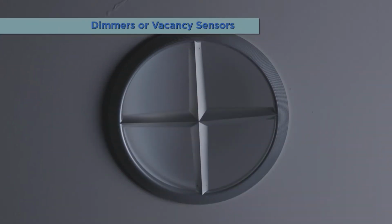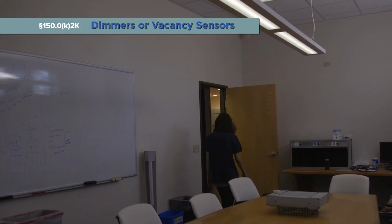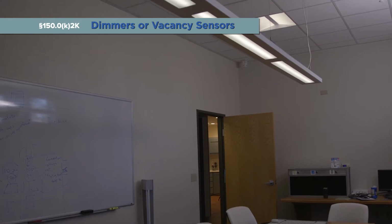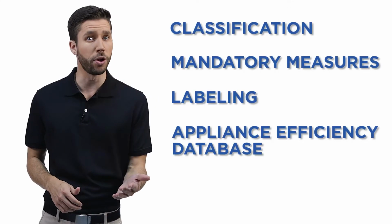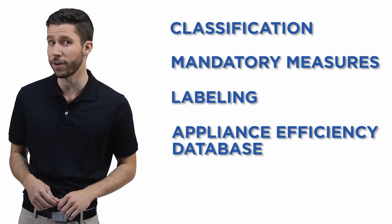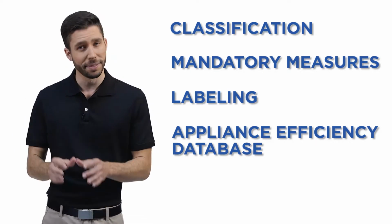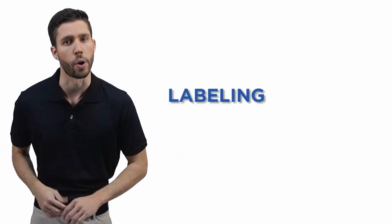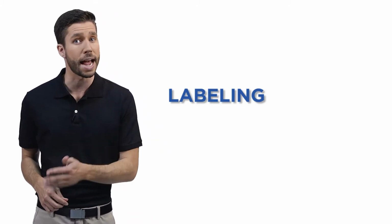There are also mandatory control requirements for luminaires with JA8 compliant light sources. All luminaires with JA8 compliant light sources must be controlled by a vacancy sensor or manual dimming control. Now that we're familiar with the mandatory measures for high-efficacy lighting contained in the 2016 Energy Standards, let's turn our attention to the labeling requirements for high-efficacy light sources certified under JA8.